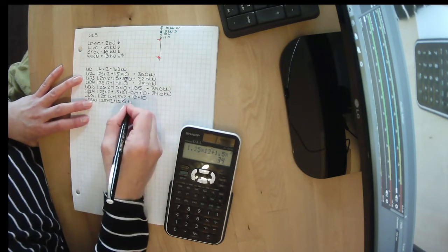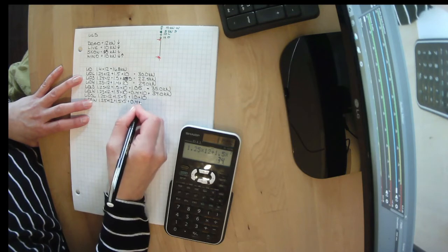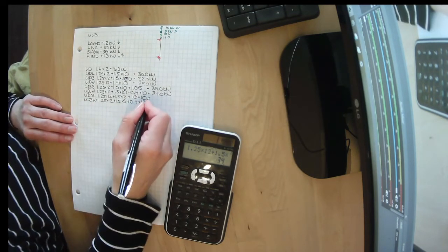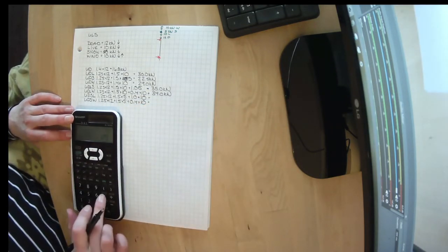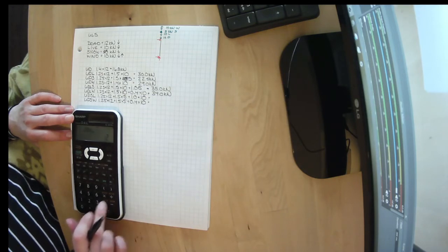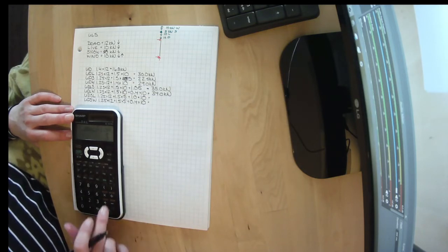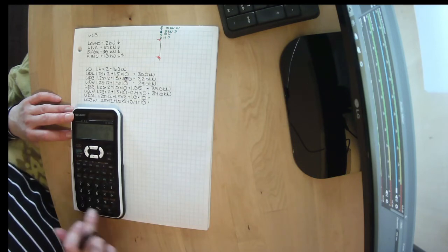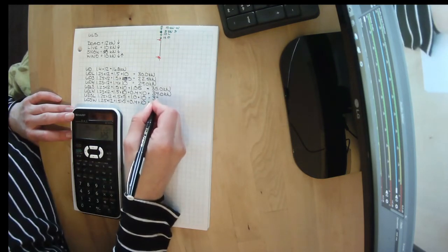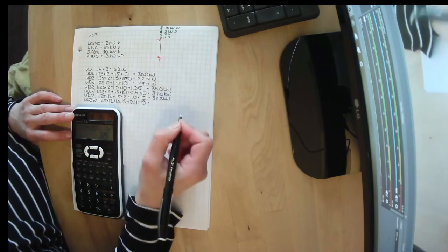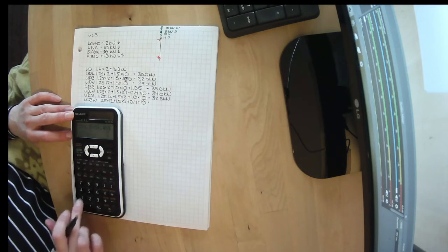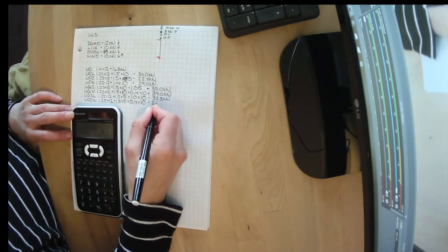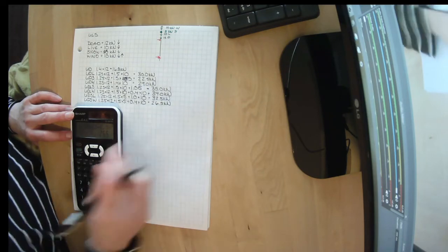And then wind as our companion load, which is 0.4 times 10. We can calculate these. 1.25 times 12 plus 1.5 times 5 plus 1 times 10, 32.5 kilonewtons, or 0.4 times 10 is 26.5 kilonewtons.